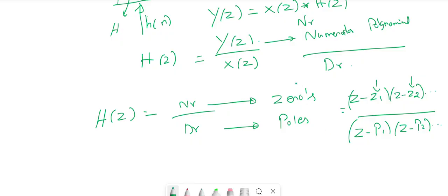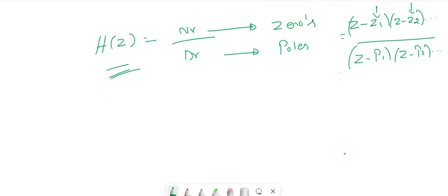As I said, our system should not operate in the infinite amplitude mode. So we must avoid operating the system in the region of poles of the transfer function. Now, for a given function, you should be able to find the poles of the system. And the question may be, what is the ROC? How do you determine the poles for the given transfer function?